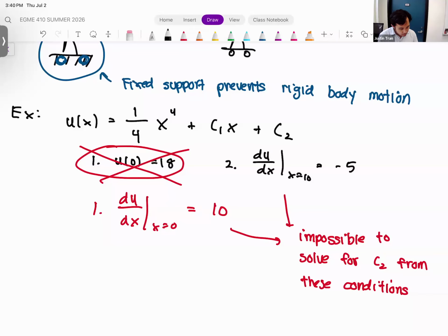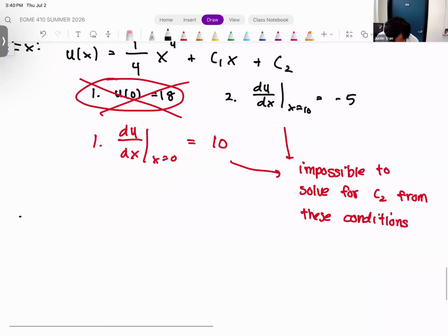All right, so before we move on to load type boundary conditions, just a few more pieces of information here. Like I mentioned, the fixed support is going to be the most common constraint that you're going to be applying in your ANSYS simulations. Another type of constraint type boundary condition is what's called a displacement.